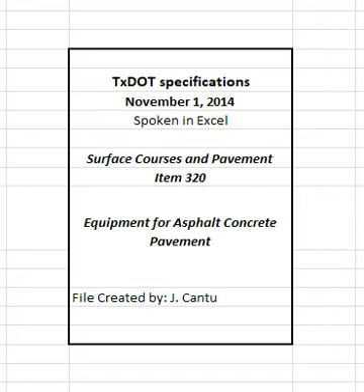2.3.1 Asphalt paver. Furnish a paver that will produce a finished surface that meets longitudinal and transverse profile, typical section, and placement requirements. Ensure the paver does not support the weight of any portion of hauling equipment other than the connection. Provide loading equipment that does not transmit vibrations or other motions to the paver that adversely affect the finished pavement quality. Equip the paver with an automatic, dual, longitudinal grade control system and an automatic, transverse grade control system.